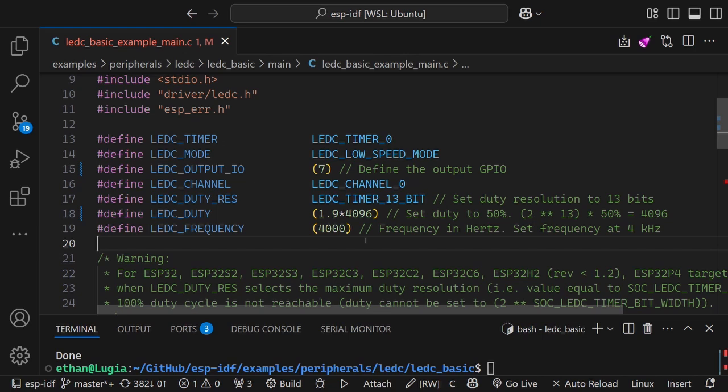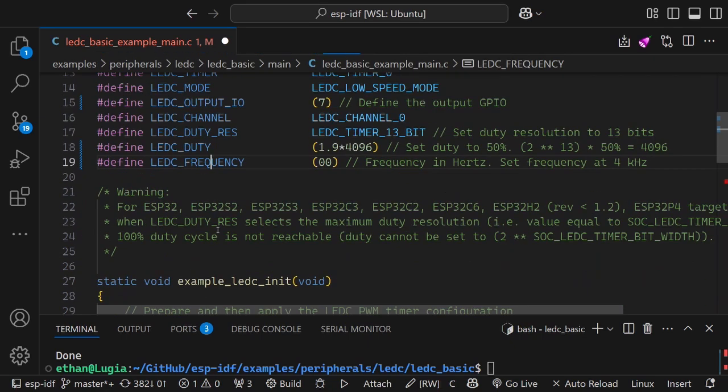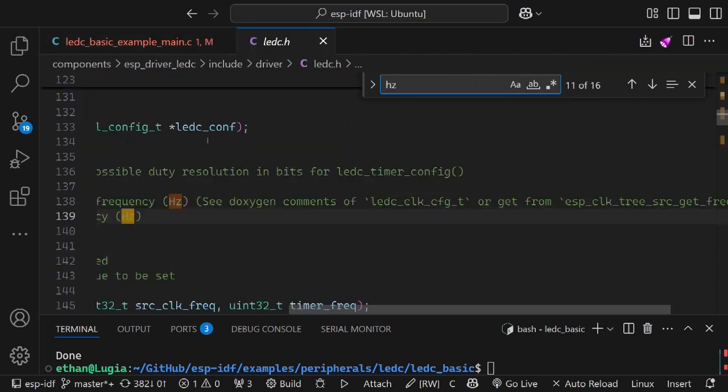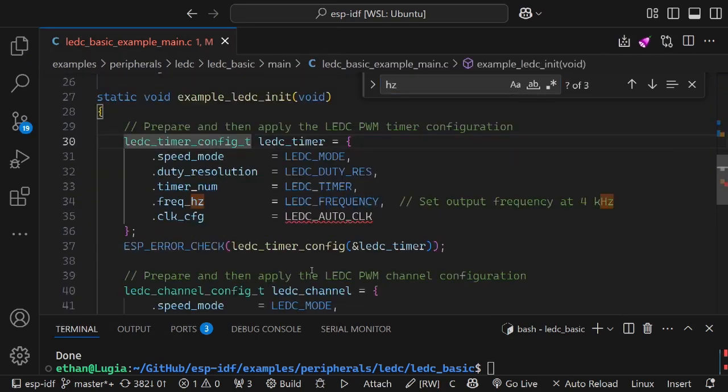If we were to turn down the frequency a lot, would we be able to see it? We actually would, yeah. Okay, let's see what happens. I don't know how low we can turn down the frequency. I think the lowest the frequency might go is still like 60 hertz or something. We can test it. Anyone want to Google what the lowest PWM frequency of an ESP32 is? I think you can go down to 10 hertz. 10 hertz? Okay, let's try it.